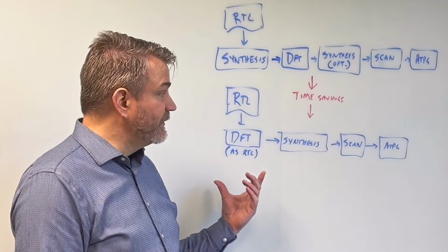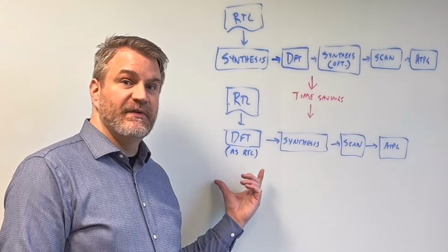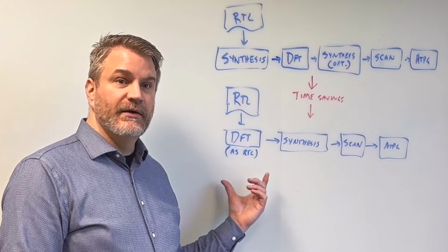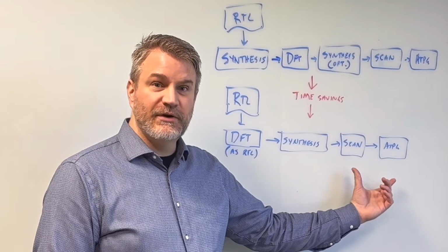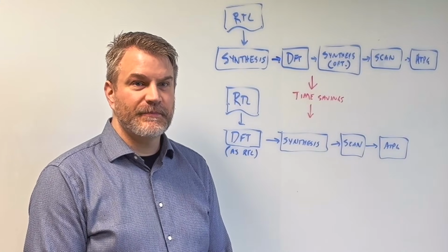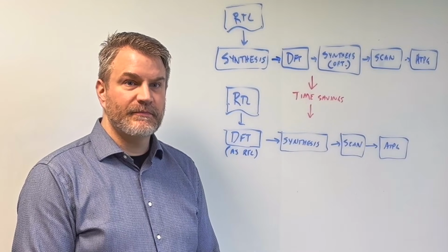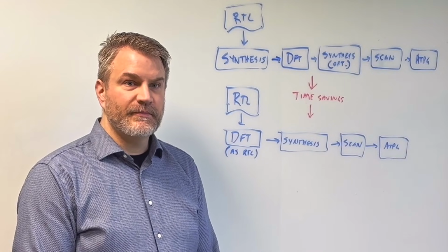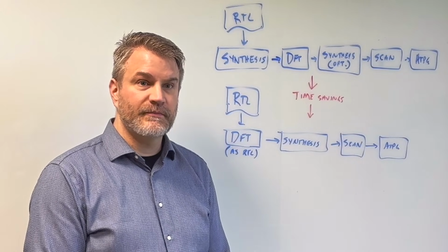Where that allows us to shine is that as the design changes, you can adapt DFT to the design. And so you no longer suffer from having to do all of your ECOs and then change the DFT logic late in the game. As you start getting into 2.5D and 3D designs, though, DFT becomes significantly more important, right? Because you can't necessarily get to all these parts that you need to test for.